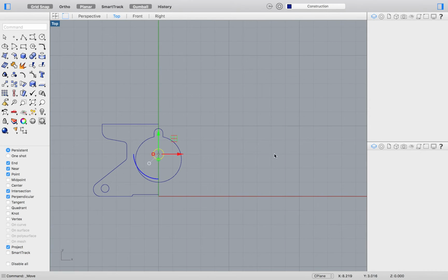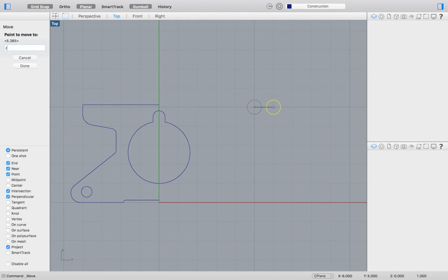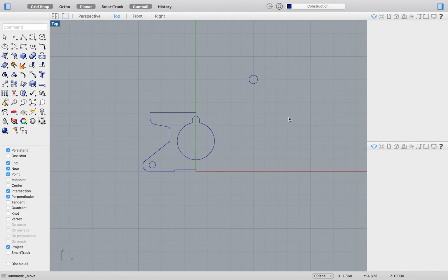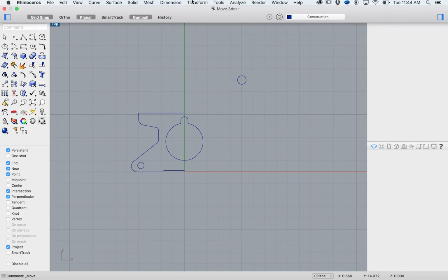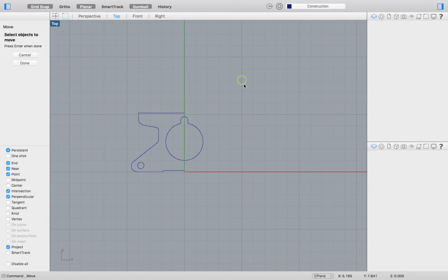Now we can perform the same action again, this time using the relative coordinates 0, 3, but first type R to indicate these are relative coordinates. As you can see, there is a very big difference. Using a different starting point will certainly also have an effect on what points you move to. Now we will move on to exercise 37, which covers copying objects.